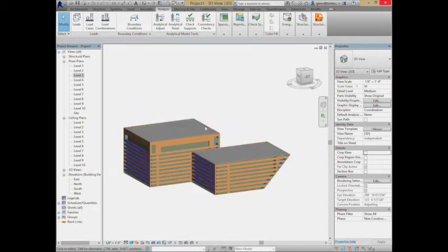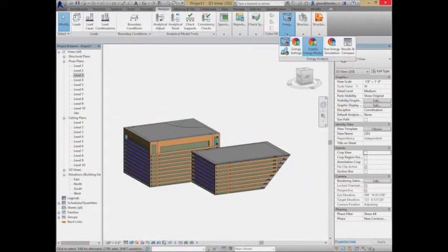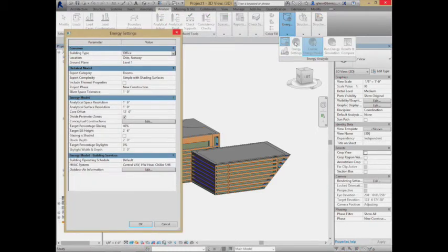There's some other assumptions here that you might want to play with, or that we'll learn to play with. One is this notion of, is the building divided into something called perimeter zones? Just so you know what's happening with that, this is perimeter zones and core offset. In most buildings, if you have interior walls, up to a certain distance away from the windows is really more controlled by the window surfaces. Within a core, though, it tends to be more constant temperature.